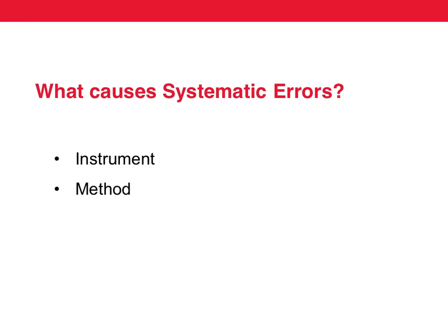The interesting thing about systematic errors is that they are very difficult to detect. The only way to find out if there is a systematic error in the measurement is to use different instruments or different methods, or to get different people to do the measurements. We do not know the errors until we compare it with the measurements made by another instrument or method or person.